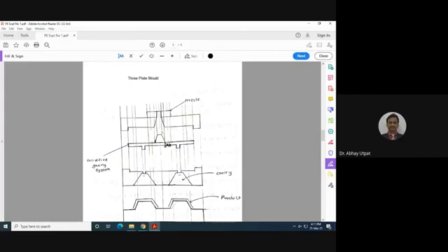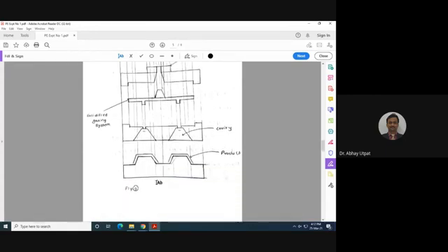So injection molds may be 2-plate or 3-plate. A typical 3-plate mold is as shown in figure. If you consider top as the first plate, then in between first and second, there is an injection mechanism, and between second and third, there will be the product, actual product. And then ejector mechanism is not shown here.